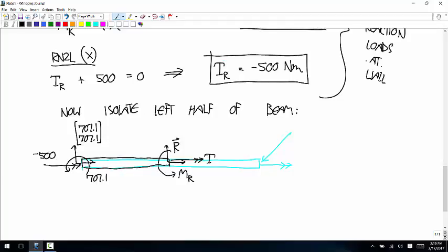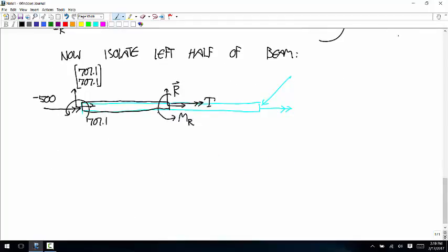And so now if we add all these up, set them equal to 0, we can calculate those loads that are applied to our chosen part of the beam by the part that's not chosen. And notice that these external loads don't show up in any of our equations or our free body diagram, because these are applied to something that we're not isolating.